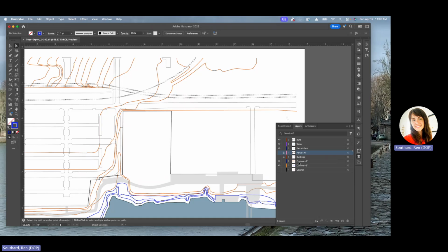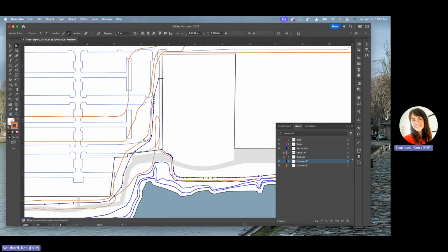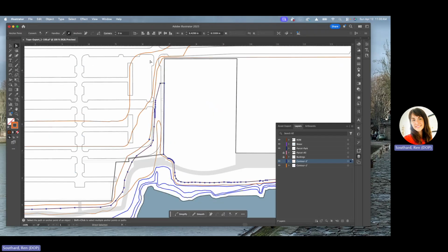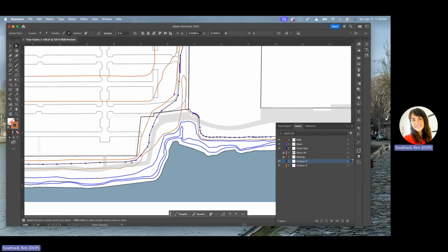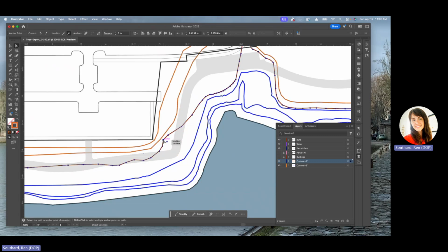And then I have these two contour layers here. This coastal layer, I do not need. That's the buffer zones. And for my 3D model, I don't need that. I'm going to delete that. And then I've got these two different contour groups that I'm working on. What I'm doing is just pulling these a little bit off of the lines for the right of way. And typically you would not run a contour line down the middle of a sidewalk. So I'm doing some regrading exercise here to put the topography either below or above the sidewalk as part of my cleanup.